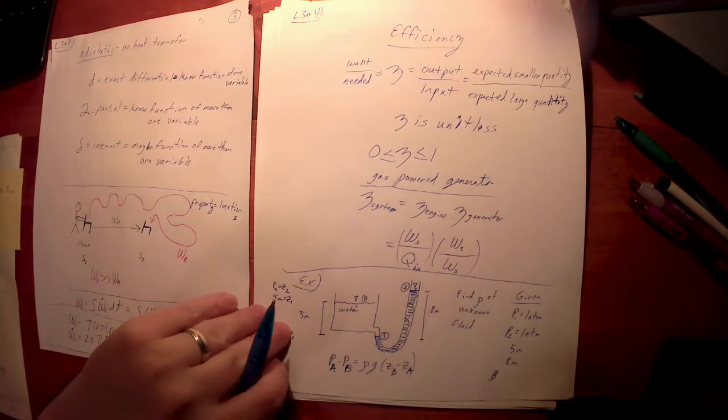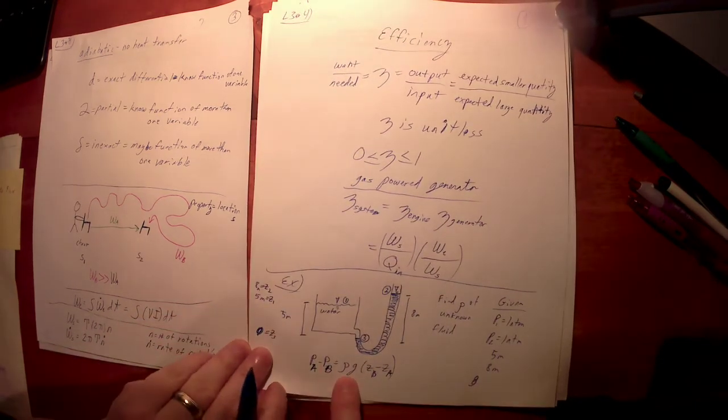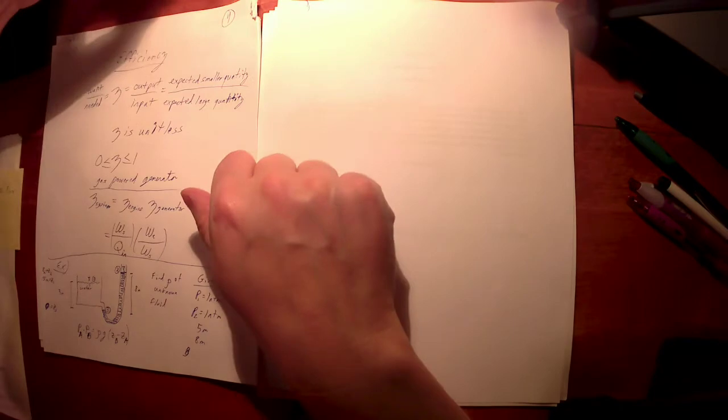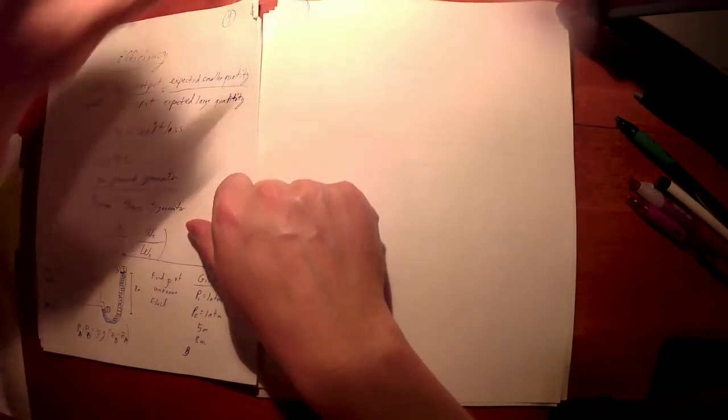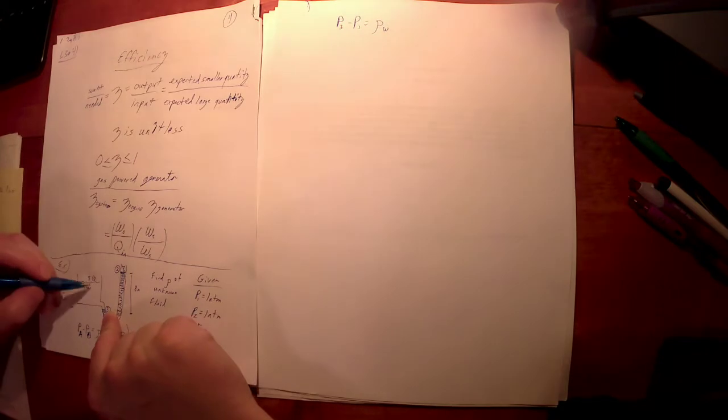Now, Steve, how the heck does that help us? Well, again, this expression will get us through one column of fluid with one density. I've got more than one column of fluid with more than one density, so I just need more than one equation. So here's what I can do. I've got the same fluid between points 1 and 3. So P3 minus P1 is equal to the density, in this case water, because it's water from 1 to 3, times gravity times, and if I've got 3 minus 1 here, this needs to be Z1 minus Z3 there.